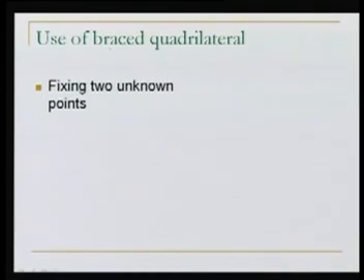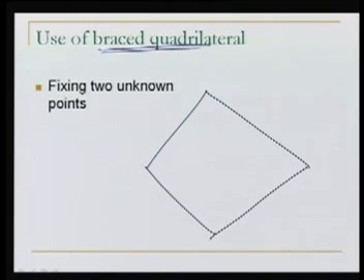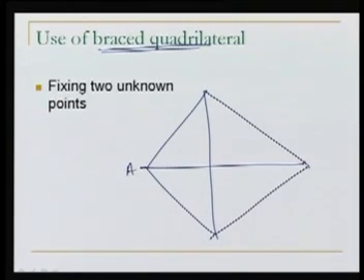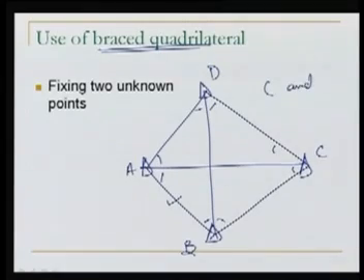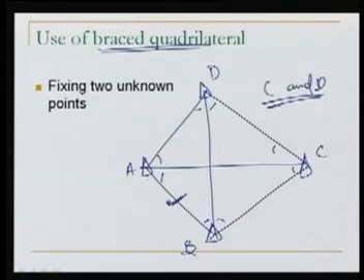Now a little bit about why we need the base quadrilateral. Basically, we know point A and point B, these 2 points are known, so this length is also known. And by observing these angles, we are aiming to establish points C and D also. We want to find the coordinates of C and D. This is very important when we are doing control survey, because we are extending the control. By knowing the length AB, or the positions of A and B, and taking these angles into account, we can compute the positions of D and C.